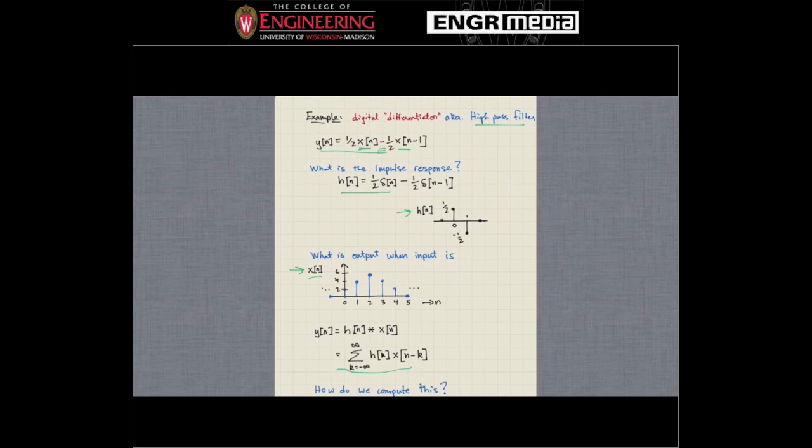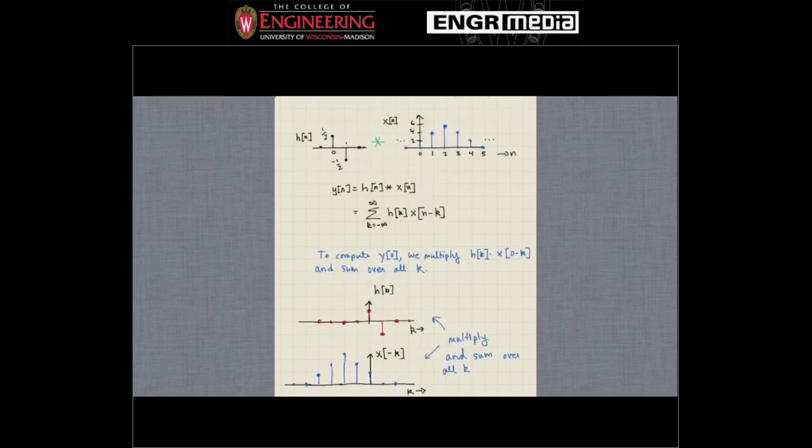We're going to step through this and be as explicit as possible here. I've redrawn things at the top of the screen, convolving the signal h of n with the input x of n. These two signals are getting convolved together. To compute the output y, let's just start with a particular value of n, say n equals 0.